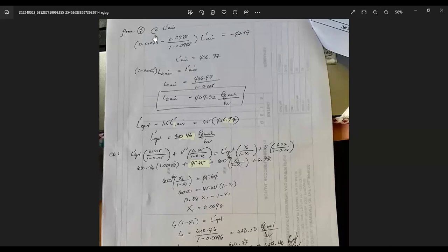So if you go back to equation 4, as shown to you a while ago, you substitute everything. This is your minimum solvent requirement. However, class, you see this L prime minimum just refers to the water. Your solvent, remember, that enters the column is not pure water, but it has 0.005 mole fraction ammonia.